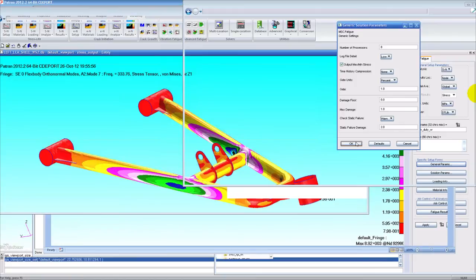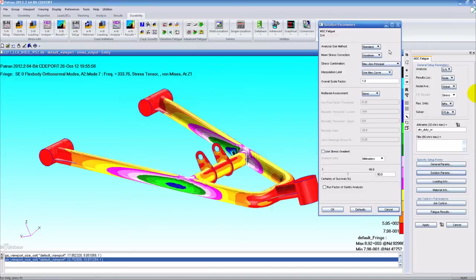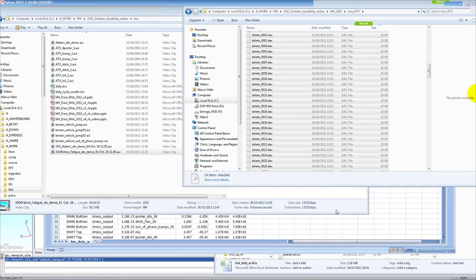In terms of SN analysis, of course, I have multiple options. I can choose different types of material modeling. The standard SN curve, the one that we've seen during the presentation, is the one that we're going to be using today, but we could be using more complex material systems such as multiple mean curves, multiple R ratio curves, Haigh diagram, and other options as well. So I've already been introducing, sort of pre-warning you about, the selection of max absolute principal. So this has been clarified enough. Other possible selections are signed von Mises, or signed max shear, or critical plane. Let's again skip through the other additional settings that are not too important at this stage.